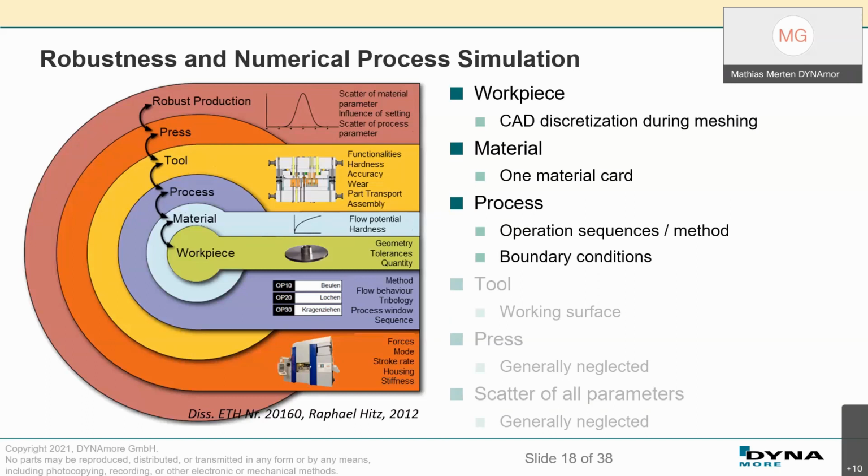And 10 or 20 Kelvin difference in the temperature can dramatically change the yield behavior of that material. And if you are producing a lot of parts, your cold forming tool also gets heated up, and therefore let's say the last part of your working day has a different temperature field than the first part of your working day, and so it is a different material you are using.